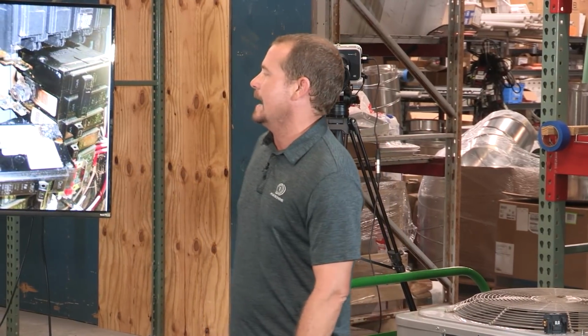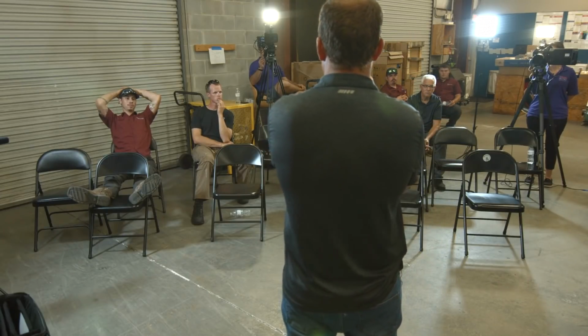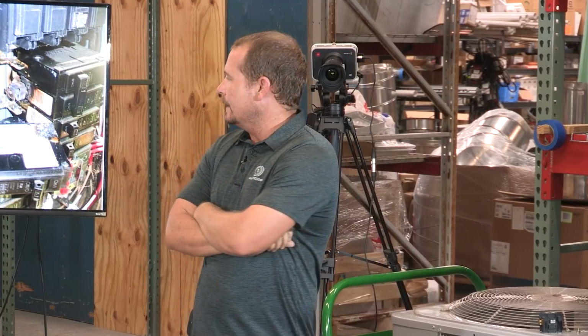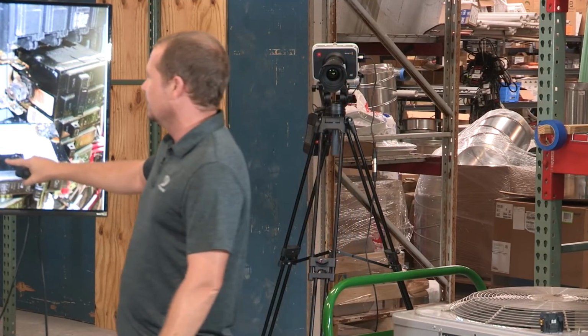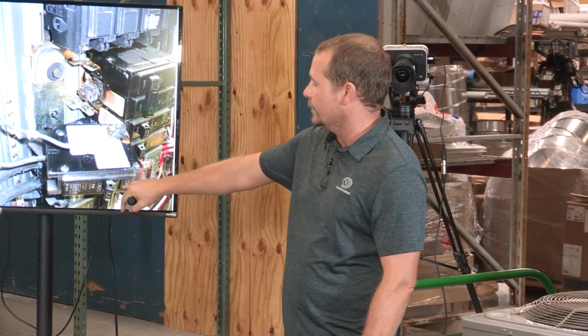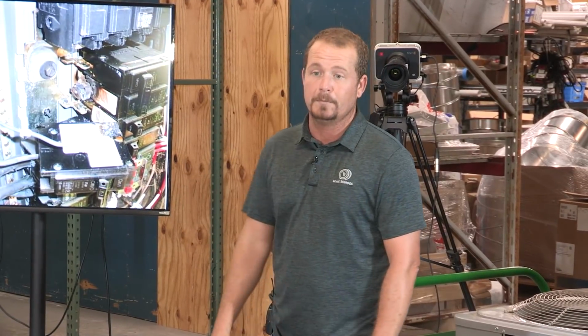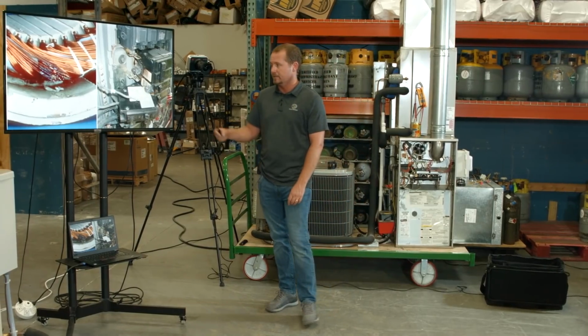What other reasons could this happen other than poor contact? Properly sized. It's possible, and actually there is one factor here. In some cases, people will try to jam much too large of wires underneath breakers, and then they end up cutting strands off or whatever, and so that can create a hot spot. That can do it. But more than likely it was just a poor connection. But you could have a breaker that just didn't trip, and it had really high current on it over an extended period of time. That can also happen, potentially. Most likely, just a poor connection.